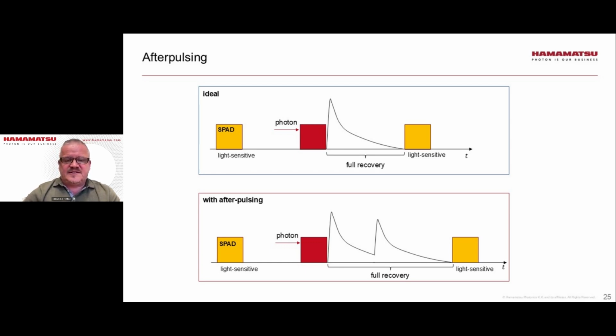However, in a realistic SPAD, what can happen is that during the recovery, shown at the bottom panel, I can have an additional pulse produced. So this is known as afterpulsing, and this pulse is going to have lower amplitude than the primary, and it's due to a charge being released in the SPAD's crystal structure producing the secondary avalanche. So again, afterpulsing is also a reminder to us that during recovery, the sensitivity of a SPAD is not zero. If it were, you would not have afterpulsing.